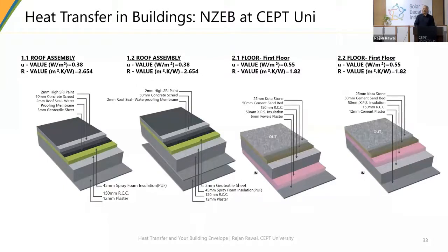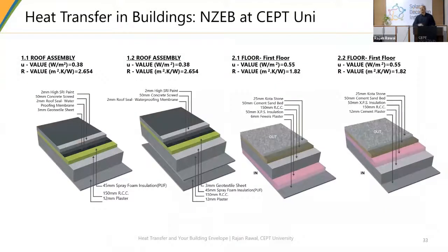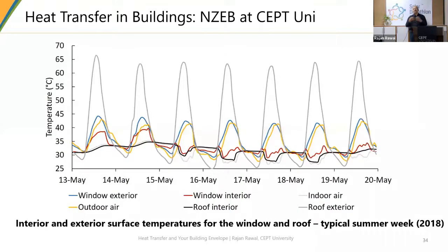In a similar way on the roof, we have waterproofing, then we have RCC, waterproofing, and then we have a foam PUR, which is a single piece of insulation from one end to the other. But for intermediate floors, probably the floor which you see as intermediate, which is a naturally ventilated floor on the ground, does have the assembly which you see on number 3, because it is in a manner an exterior floor for the first floor, and hence the insulation was kept on the soffit of the ground floor, which makes it sort of external insulation. And how does it operate?